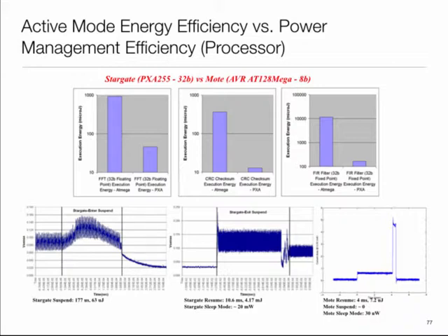Have two cores. Okay, yeah, you're on the right track. So you switch the task from one to the other. Right. So kind of the concept is the big core is powered off. Not simply suspended, because it consumes tens of milliwatts there. It's powered off, and then whenever we need it, we wake it up and transfer the stuff to it. But otherwise, this rapid wake up and all is happening on the small guy. So we always are on the lookout for that. Should I wake the big core up?